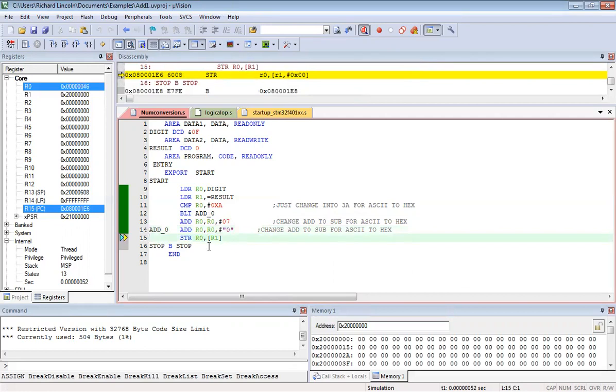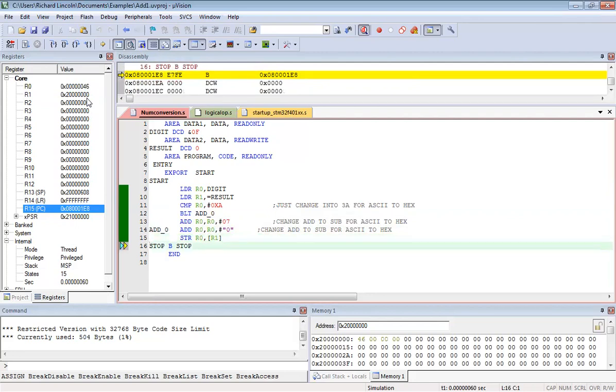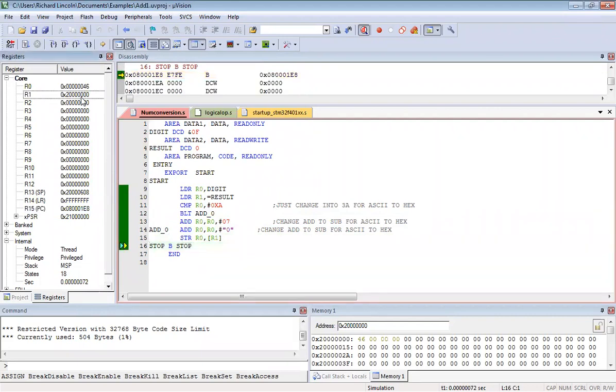Okay. So finally, you can see that R naught is having a value of 46. So remember, the conversion was 46. The final value was 46. So whatever is in R naught is being sent to R1. So this 46 should come here, right? So if we go to this location here, 2000 and many zeros, I have pointed out here. You can see that its location is updated to 46, the value.